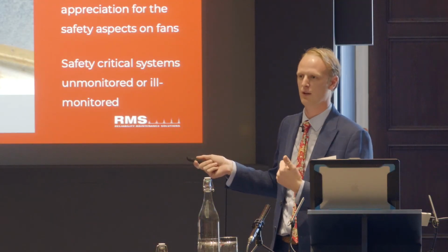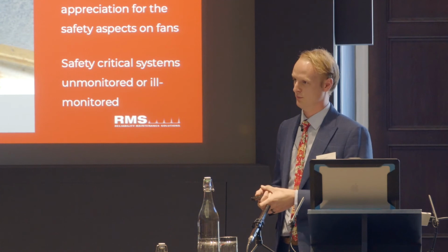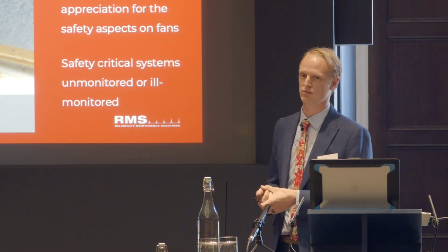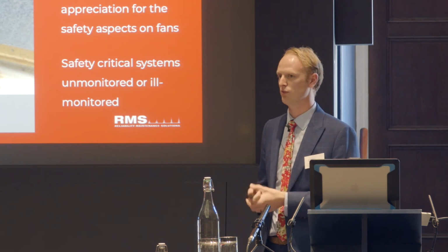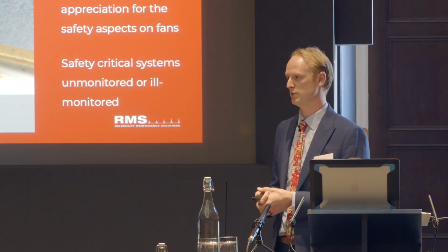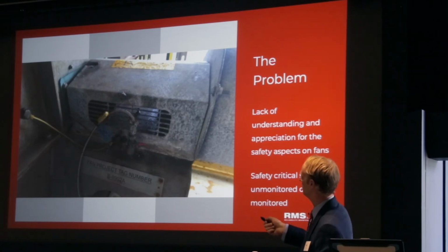In that previous fan, we weren't allowed to mount the sensors on the bearings where the fan is mounted. So when that fan let go, there was no monitoring on it. And that's what we see often in industry, that fans like this run without any monitoring on them whatsoever. When we do see monitoring on them, often we see this problem.